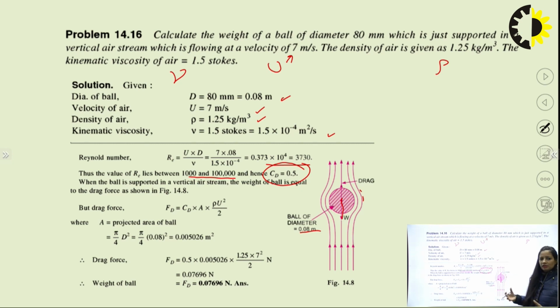Drag is what? Simply whatever force the air applies over that particular ball is drag. Okay, so the next step is your drag force. How are you going to calculate drag force? As CD times area times rho u square by 2.